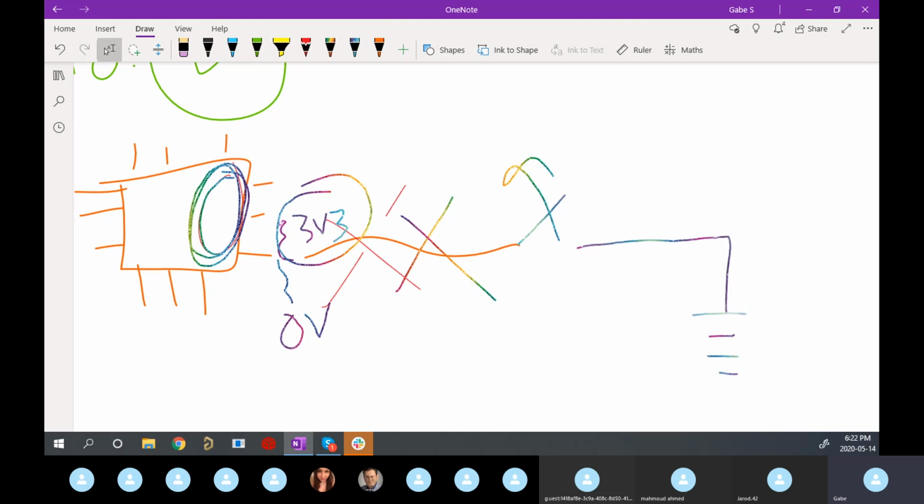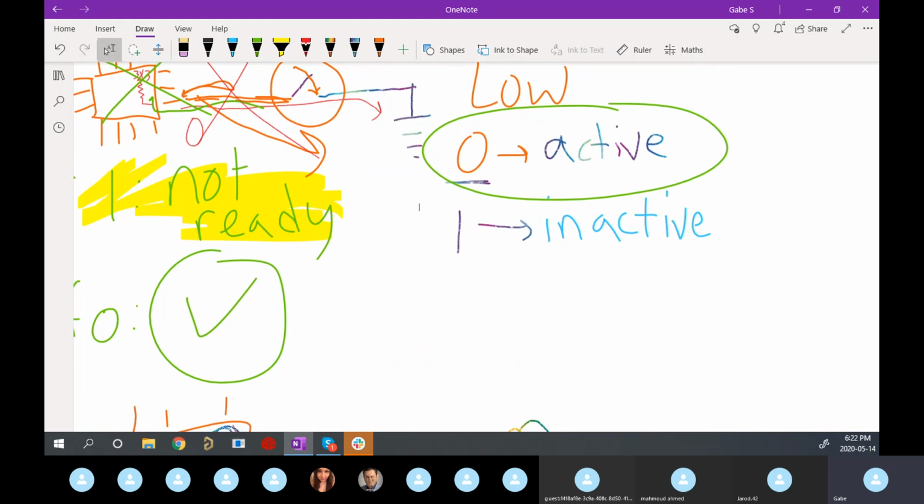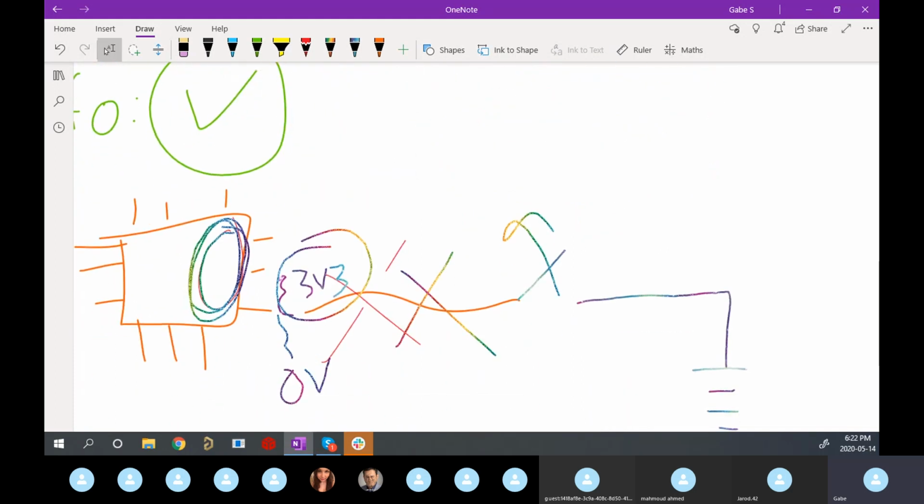And so we never know what that pin will float to. Maybe it'll float to 3.3, which is inactive, and that's fine for us. So putting that pull-up resistor will give us that default state where in case something gets disconnected or we don't actually have access to the real state of the system, we're not accidentally floating to the wrong state, right?